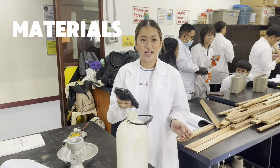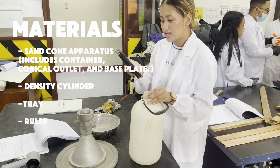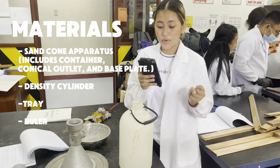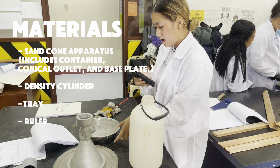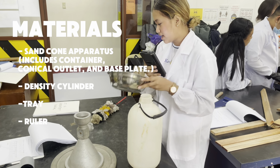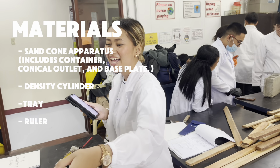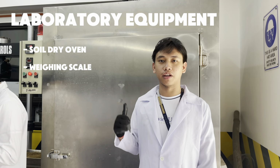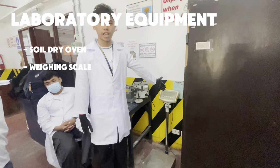For the materials, we'll be using the sand cone apparatus, which includes the container, the conical outlet, and the base plate. And we'll also need a density cylinder, a container for the soil, and a ruler. For the lab equipment, we will need this soil dry oven. Another lab equipment that we will use is this weighing scale.